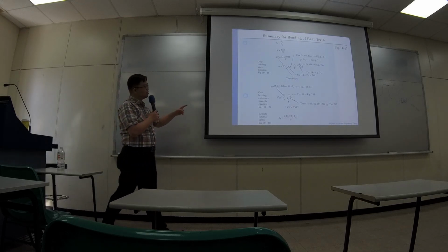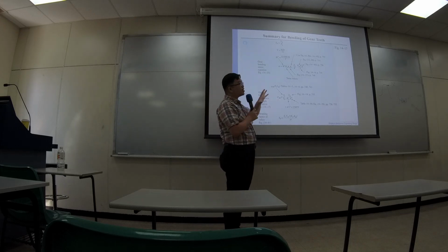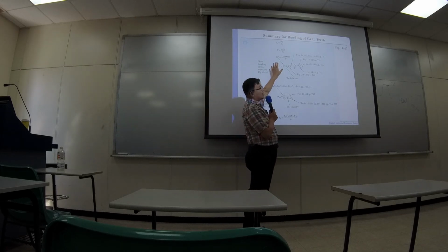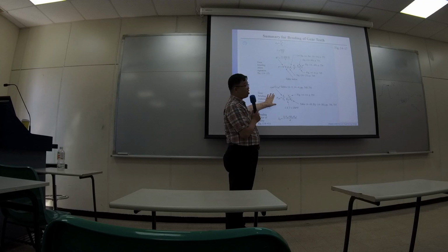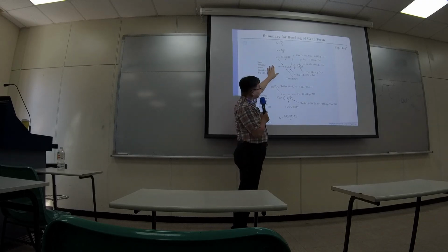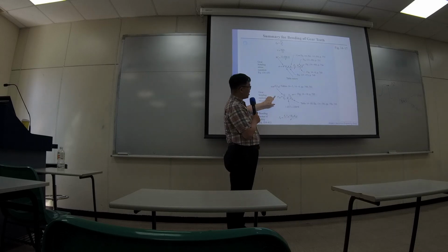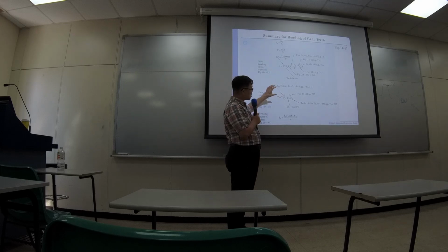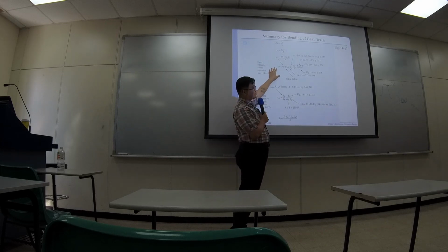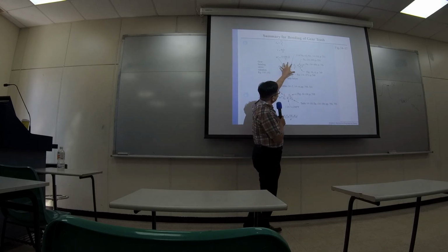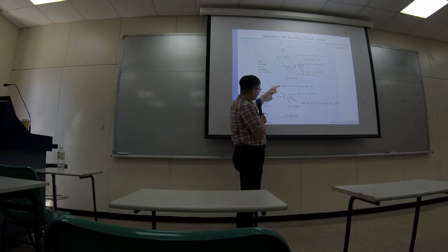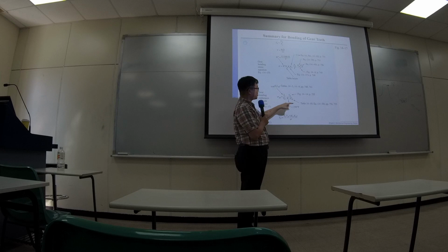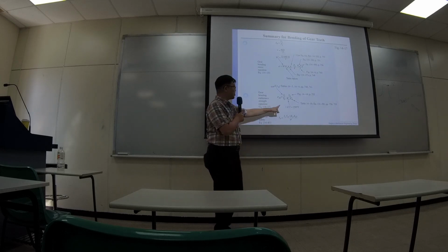And what is sigma all? At the end, this is how much stress is applied to your teeth, and this is how strong your teeth are. So this sigma is supposed to be smaller than the allowable. This is sigma all, the allowable stress. So this is how strong you are, this is how much load you carry. So in your design, this equation must be smaller than or equal to this equation. And over here, there are also factors, and also the safety factor is here, SF.